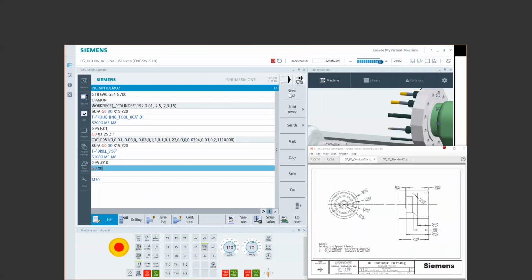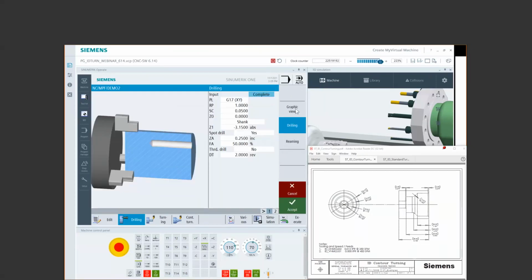You do have to look at the maximum you're allowed to be off with any given drill, but you're going to be very close to center line, right? So you've got to make sure you get it into position. Z, maybe it will be 100,000. So she's going to rapid it down to position, because when you go to the drilling cycles, you notice nothing says centric. So it's up to you to pre-position that tool. Then you can go into drilling, fill out the page.